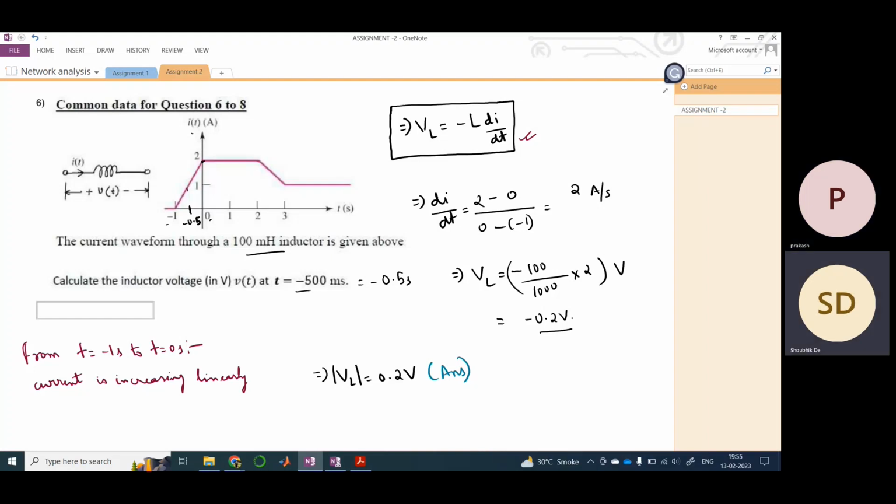This is not Faraday's law exactly. The voltage that develops across the inductor tends to oppose the current, that is, it opposes the cause which is developing it. So this is the basic law. For this problem, since you have been told to calculate the magnitude of the voltage, you can easily ignore this sign. But there is a negative sign because of the voltage that is developed across the inductor.